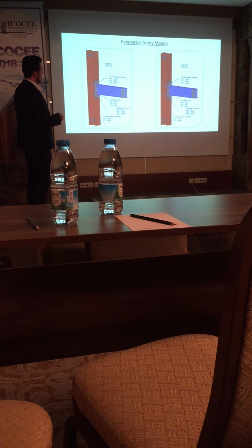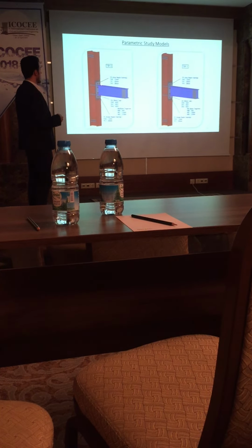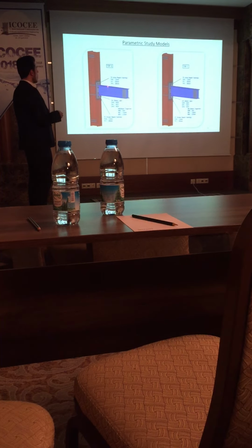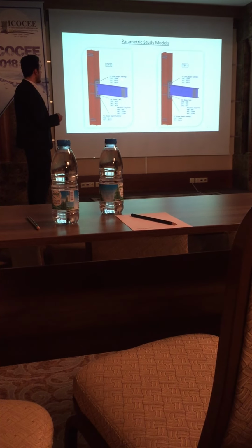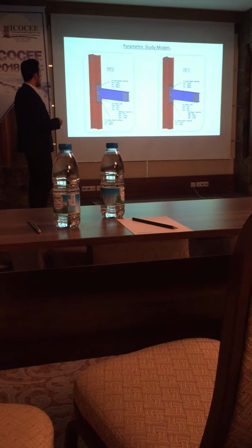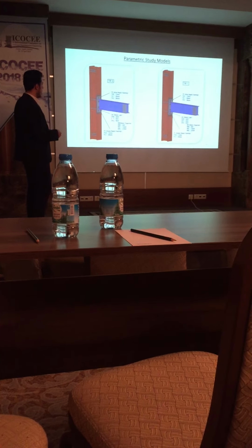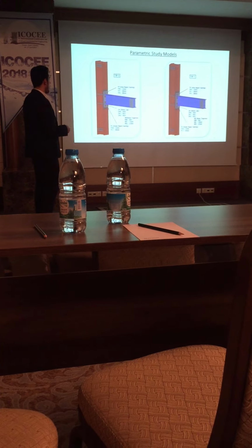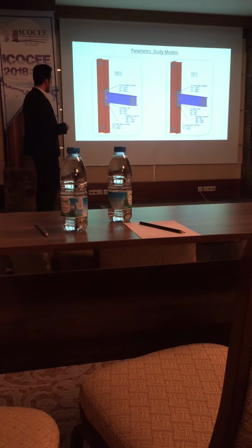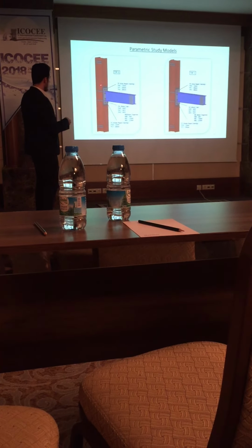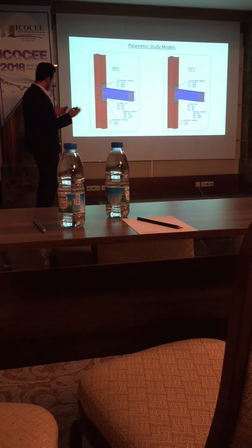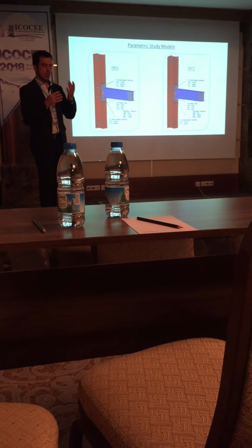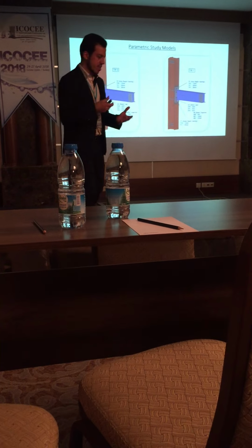In our coding system, TP0 means this is 12 millimeter, TP1 20, TP2 28, etc. And then the diameter of hole, as you see here, is changing, various stress of the bolts, and then the thickness of column. We also made this part various to see how dramatically this part is changing.